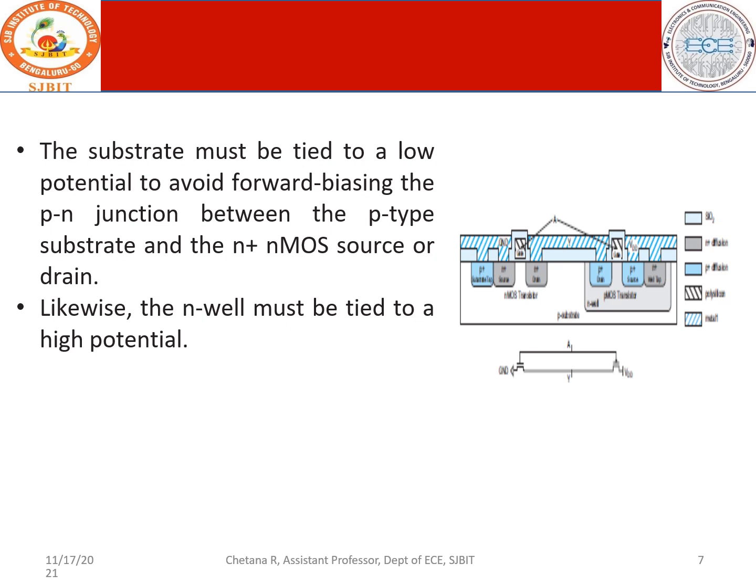So there is a possibility for so many p-n junctions to be formed in the substrate, and there is also a possibility that at one instant of time they can become forward biased and start conducting, and a leakage current flows.